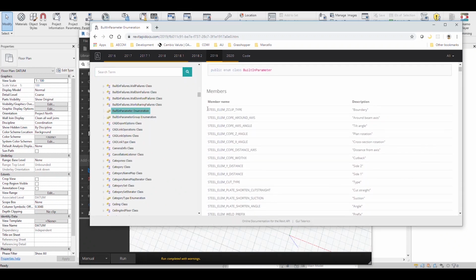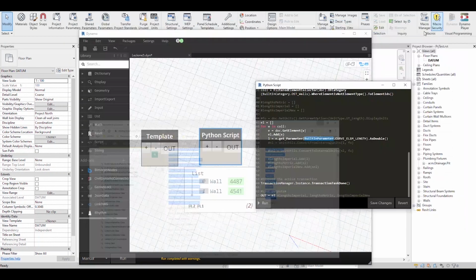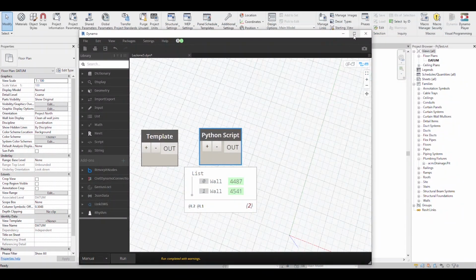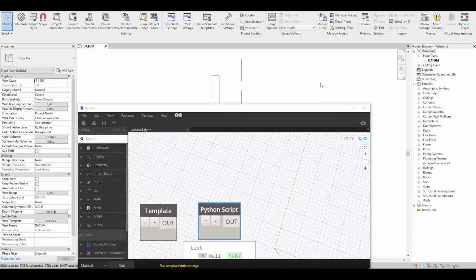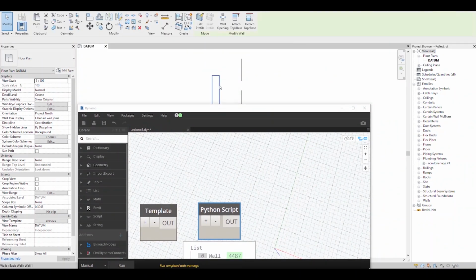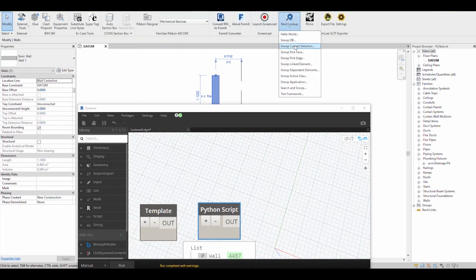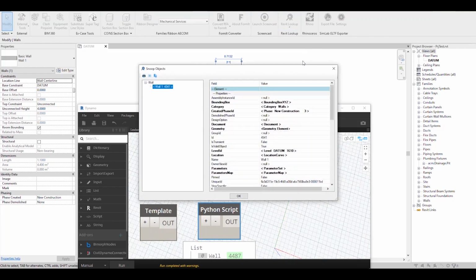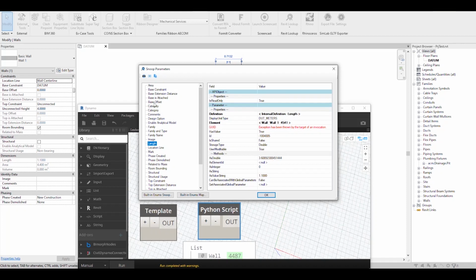And this is exactly the list of all the built-in parameters, which is very extensive. So usually, the way I can find the proper name of the built-in parameter is again going into the Revit lookup, snoop the current selection, go into the parameters, check the parameter that I need, and then there's an internal definition.